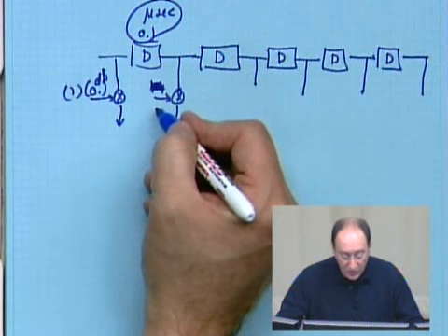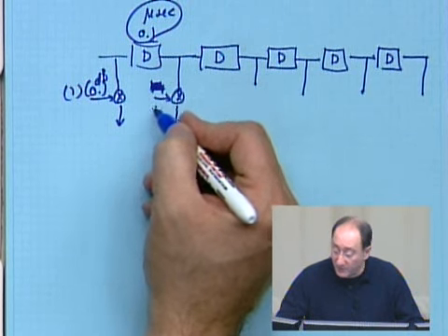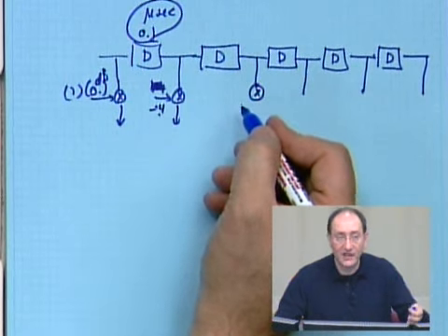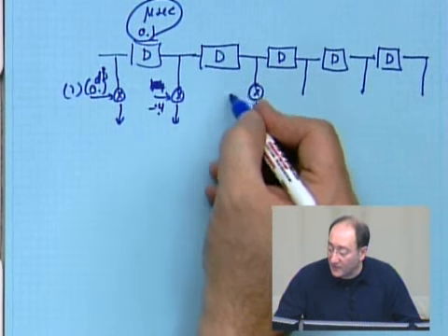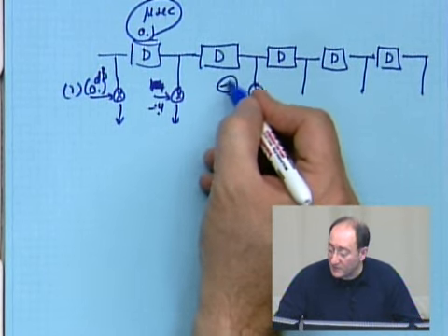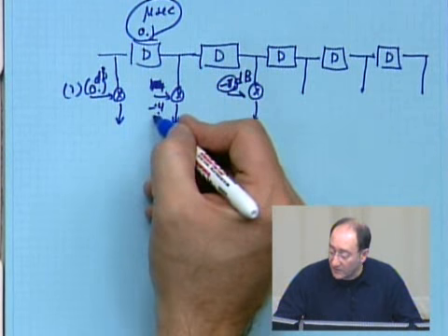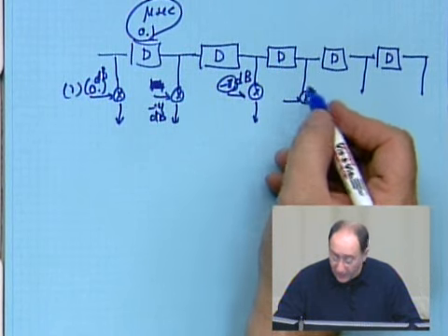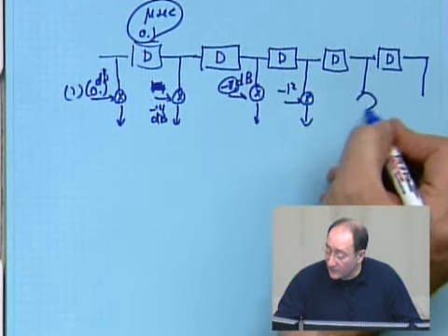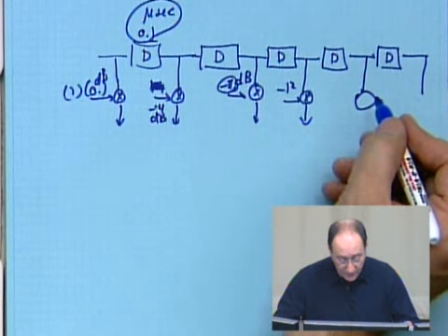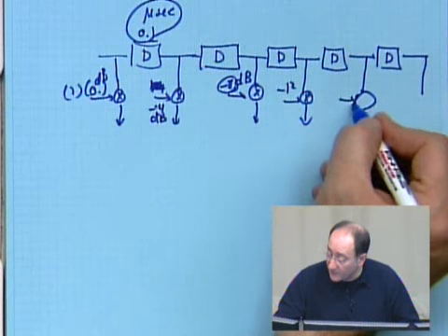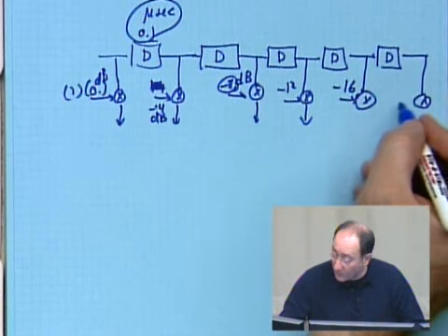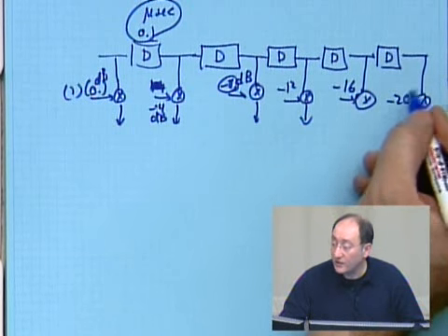But I find that. So this tap comes 4 dB below, -4. The next one is another 4 dB under that, so I multiply with that value. This is -8 dB, then the next one is -12 dB, the next one is -16 dB, and the last one is equivalent to -20 dB.